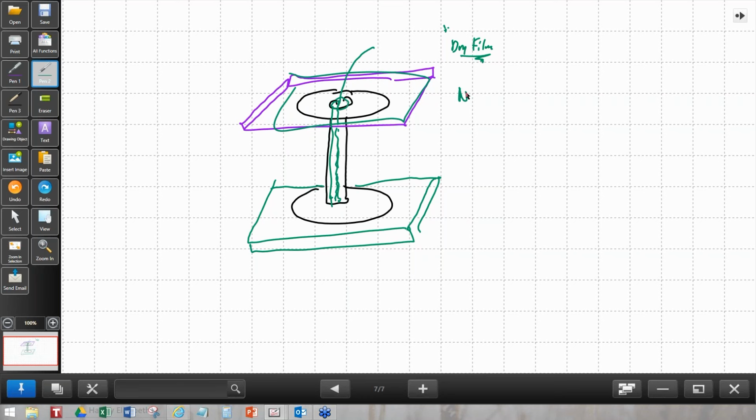Again, do not use LPI if you're going to be doing the tenting over the via holes, because what happens if 99% of the time it's tented? That means 1% of the time the top could be open, okay?